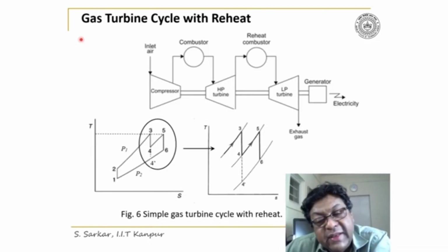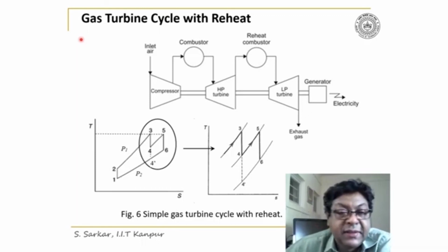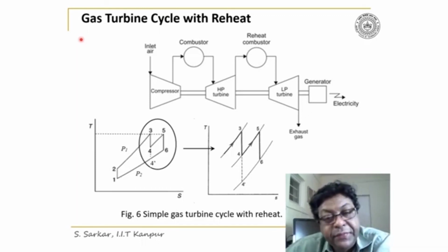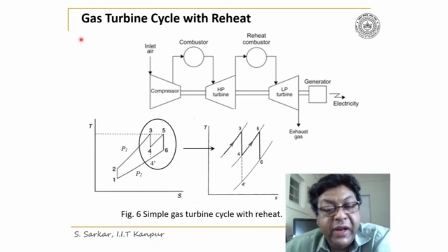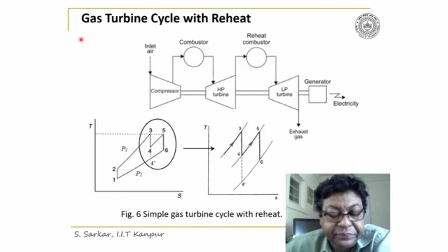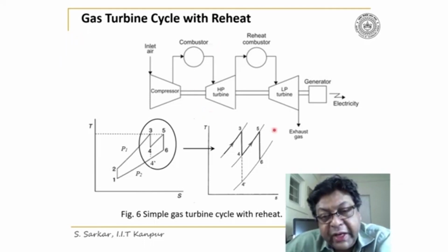I now illustrate gas turbine cycle with reheat. Reheat is done to enhance the specific power output. Look here, the expansion process has been divided into two turbines.